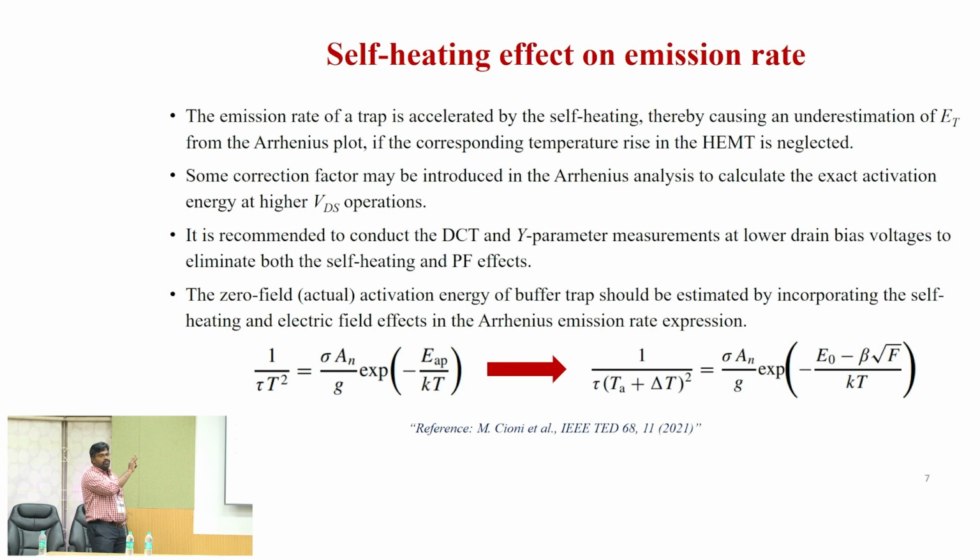By using TCAD simulation, we estimated the channel temperature. Then accordingly we incorporated the temperature difference, and we included the self-heating effect for calculating the Arrhenius analysis.